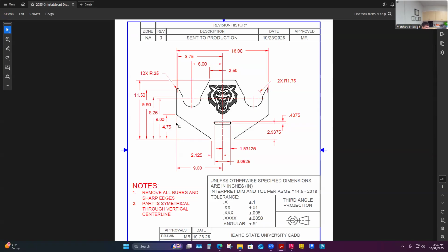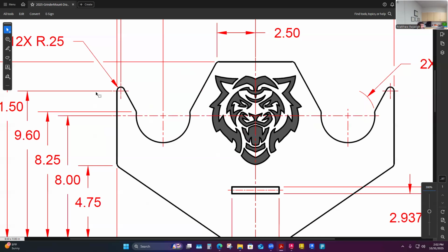I'm going to draw a line 4 3/4 up. Then I'm going to start drawing a line that's going to go past the center, and it's going to probably stop right here where this radius starts. It's hard to tell, but if I zoom into this, this dimension coming off this extension line here is to the center of this radius feature. And that's likely where this point of tangency is going to exist, a radius here to a line, and an arc on a tangent is what I'm going to draw here. So I need to know maybe how long the line is from here to there, and it's solvable here.